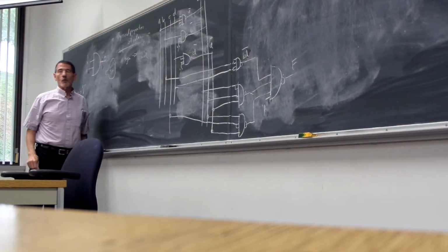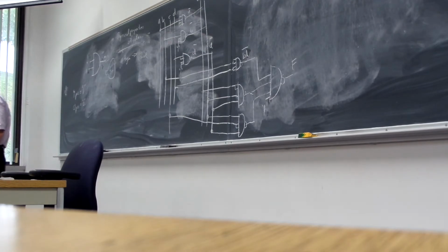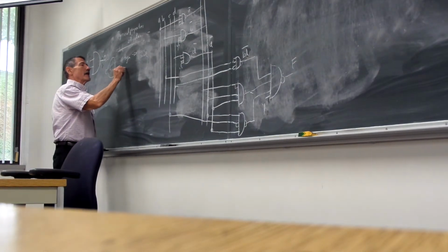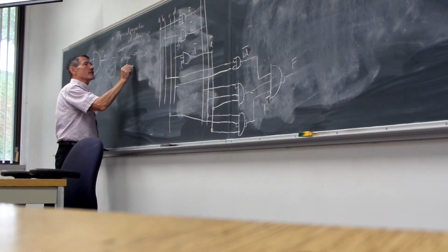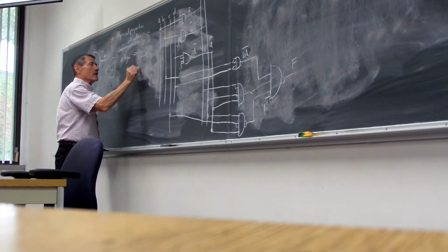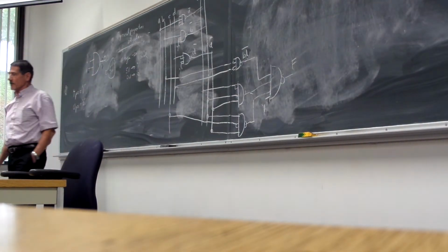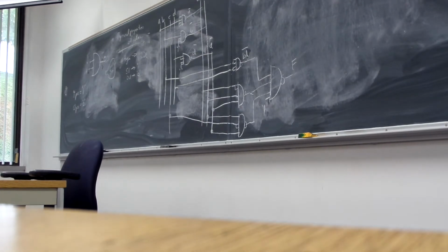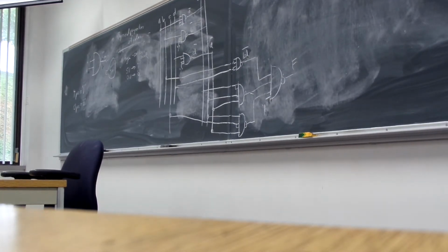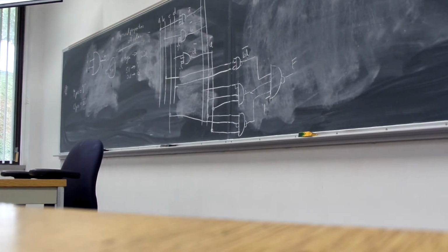So we're going to use voltage to correspond to our logic level. And typically, we're going to use 5 volts to correspond to a 1 and 0 volts corresponding to a 0. This is going to be our positive logic. We certainly could come up with what we call negative logic, where 5 would equal 0 and 0 volts would equal logic level 1. But this is positive logic.